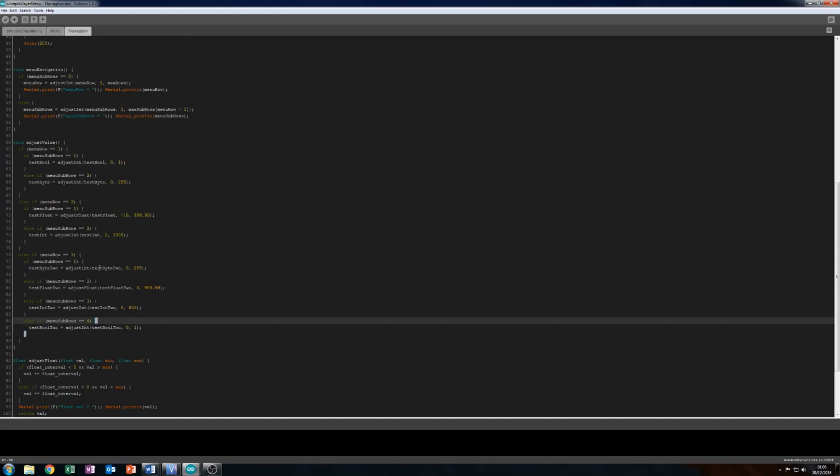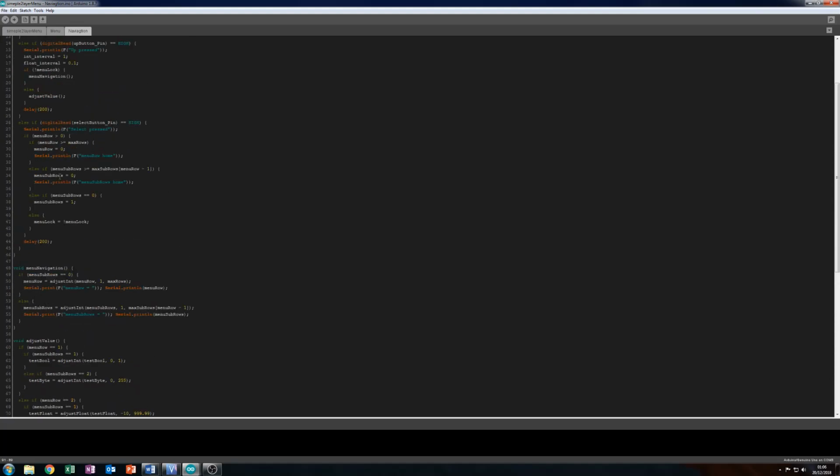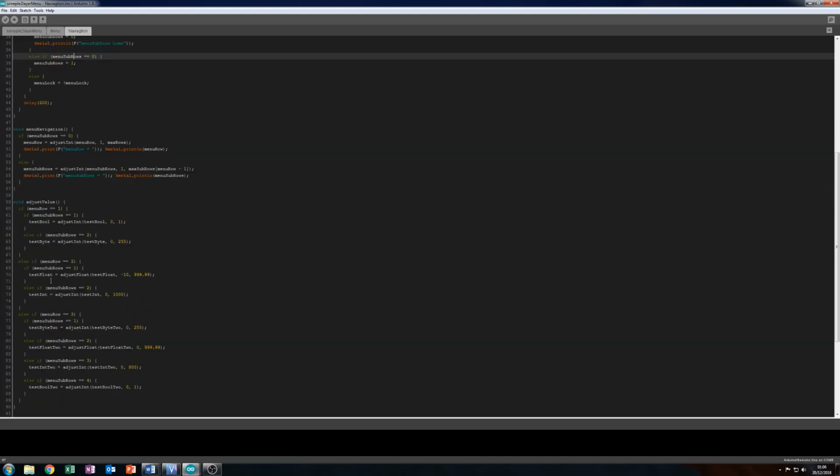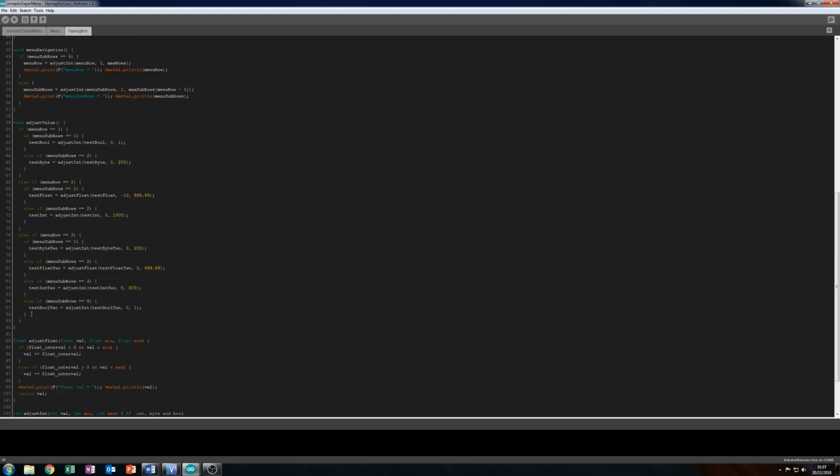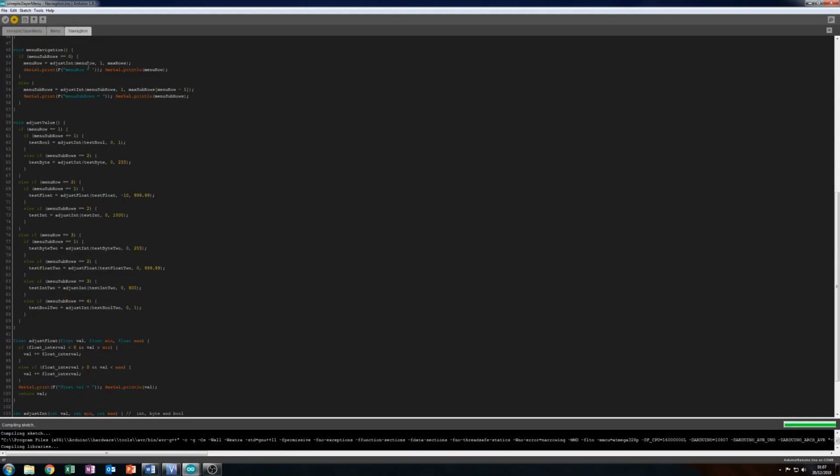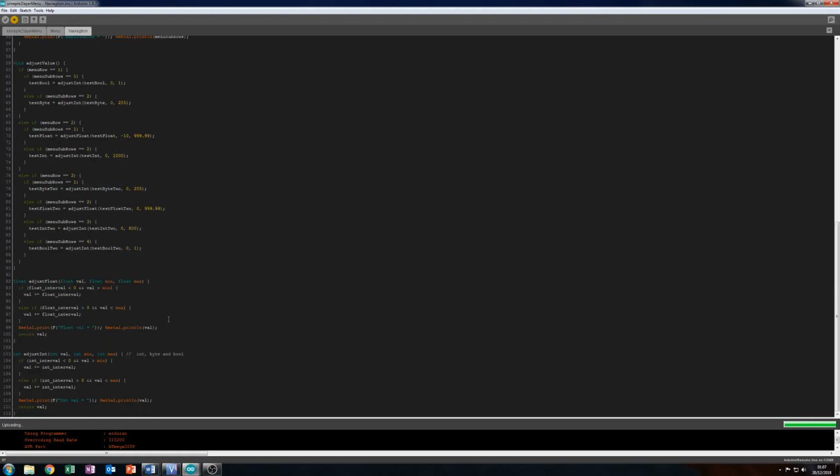And essentially that's all we've had to do. Create 2 variables and just 1 extra statement here and another statement here saying if you're at 0 and you press select, set it to 1, and if you're at the end of the menu, return it home. If you're set to 0, call the normal menu row. If you're set to 1, call the sub-rows menu. I'll show that running. I'm probably terrible at describing this, but I assure you it is quite simple.